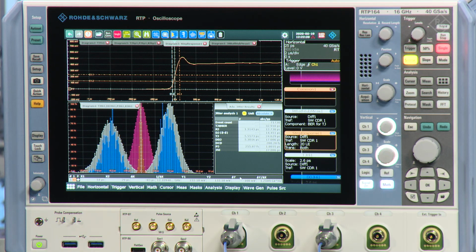As you can see, the advanced jitter analysis gives you a quite comprehensive idea about your signal, and using the step response as a new feature for R&S will give you a detailed idea about your channel, which is typically not visible in your advanced jitter measurements.